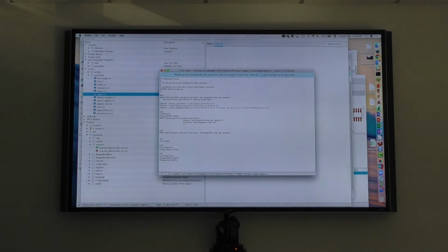If I do some changes then and close the project, close Eagle, Eagle will create an Eagle EPF, Eagle project file. The project file holds the settings of the current state. So that's only read once, really from scratch, when you start a new file.